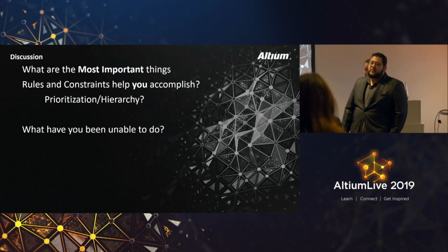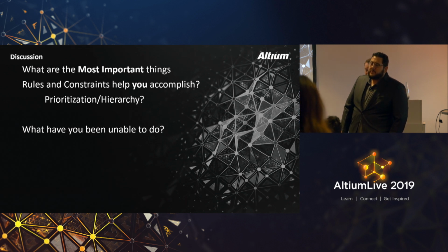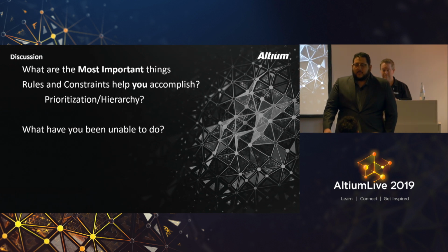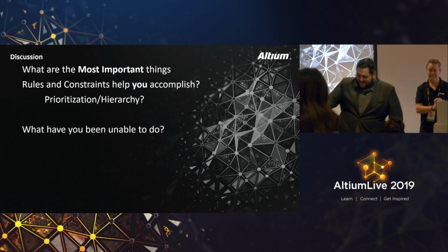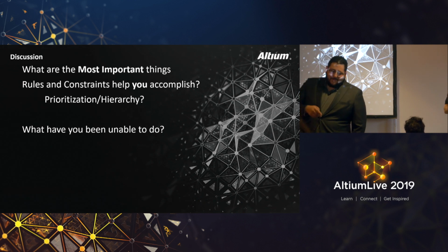But we have programmed a similar thing where we can define all the different net classes and put in a matrix the specified clearance distances, and this transforms it into 100 clearance rules at once. Okay. You understand? Yeah. That's a little complicated. You had a question as well?